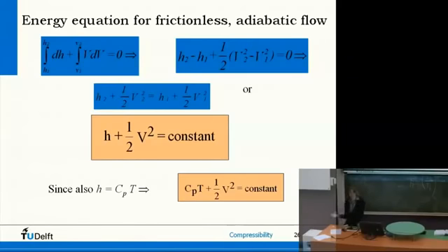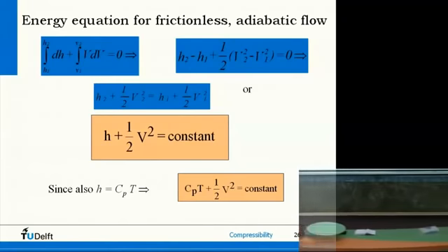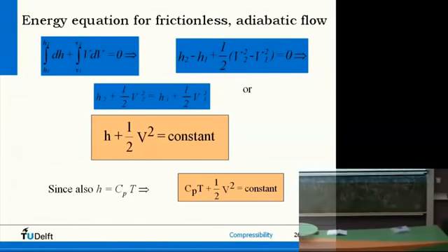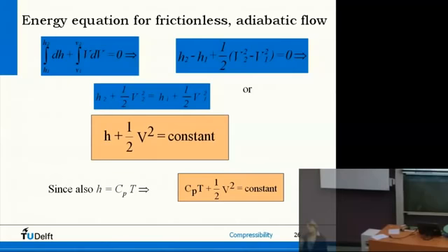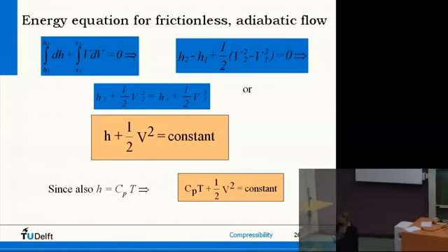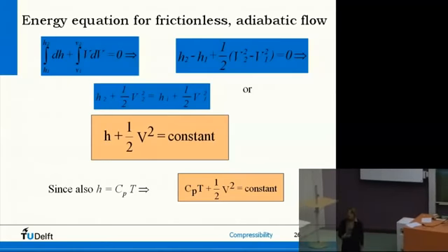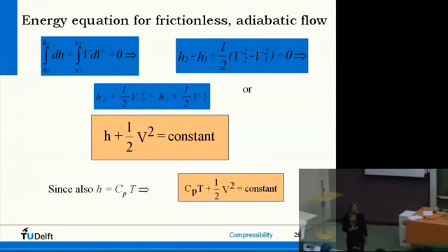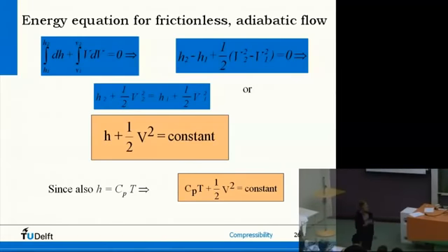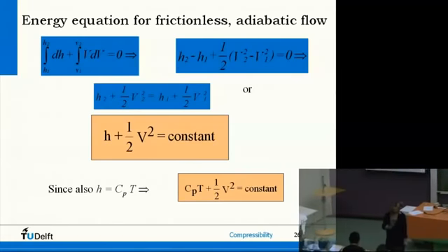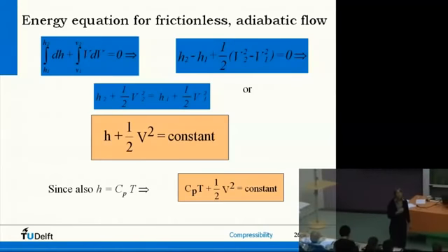So I collect all the 2's on one side, all the 1's on the other side. So I find now a relation for compressible flows, relating velocities squared, not to pressures, but to enthalpy. And what can I change the enthalpy into? Temperature. Yeah, internal energy is still a bit hard to work with. Temperatures.